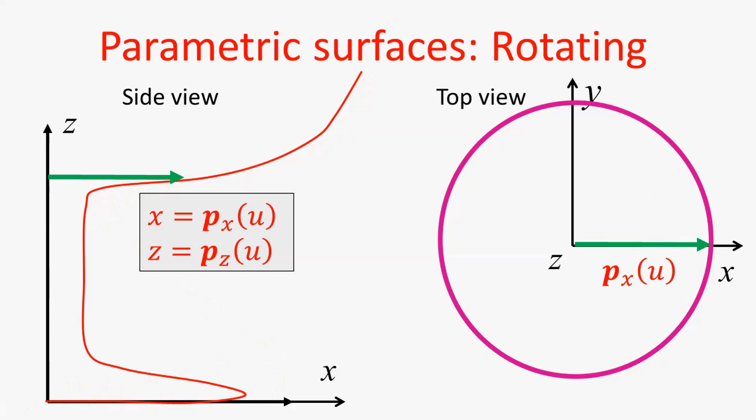So we can use, for example, Catmull-Rom spline, placing control points of this curve and relying on the Catmull-Rom algorithm to find cubic polynomials that interpolate the control points. Now we assume that the curve is a planar curve and it is in the plane defined by axes x and z. The parameter of the curve is denoted by u.